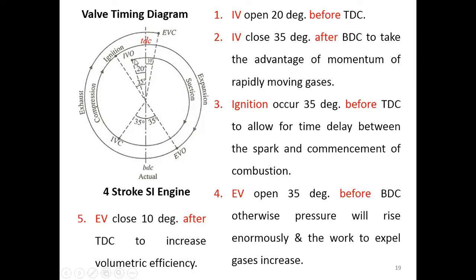So this is the distance or the time that the inlet valve is open. The inlet valve opens here, and the piston travels from here to here until the inlet valve closes.